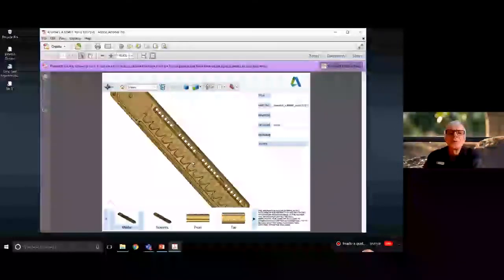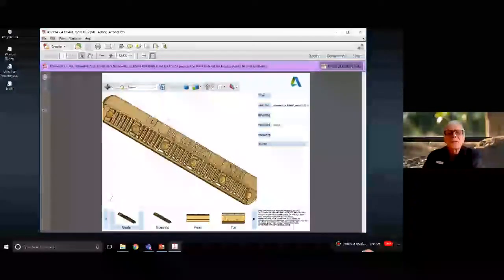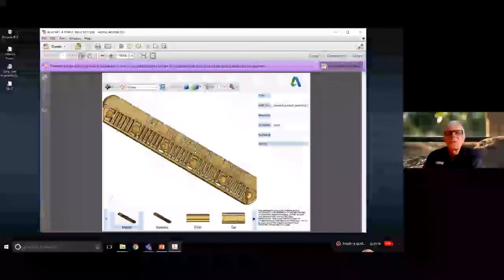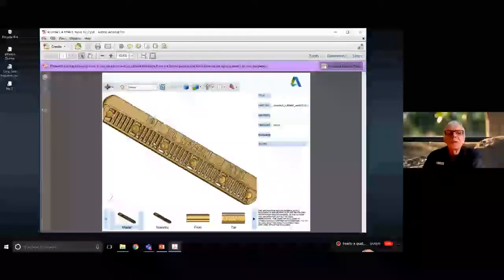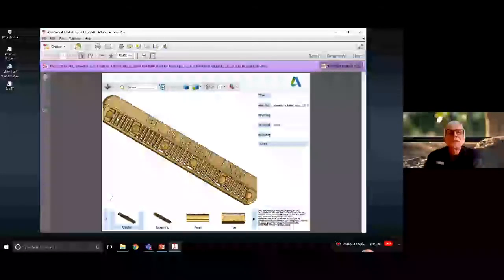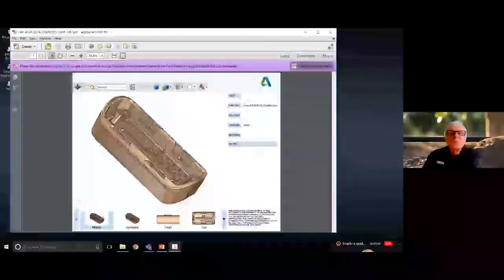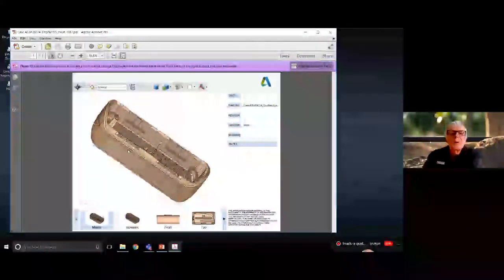Now let's just turn this over. And there you can see the vanes that serve as the filtration for this dripper. So you can see that every slot between the vanes leads to the inlet of the dripper. The ones I'm pointing to now are rather superficial, a bit cosmetic, because they're not actually connected to the inlet. So the filtration area is just taken from the sum total of those vanes.